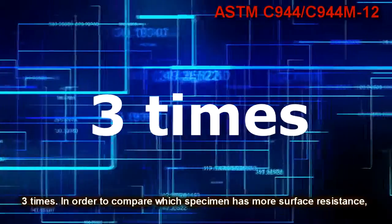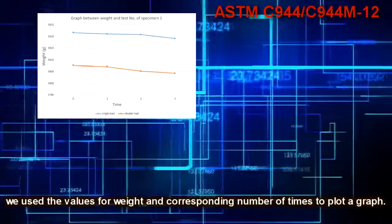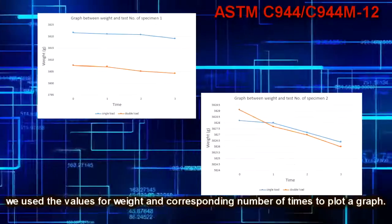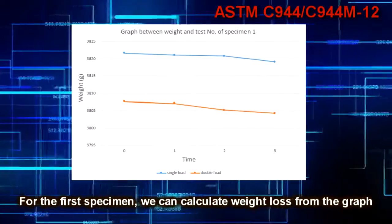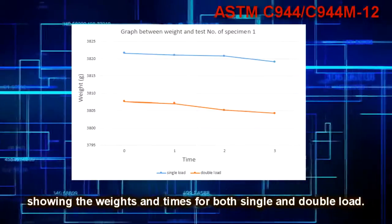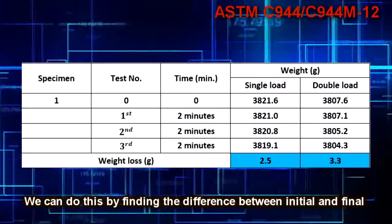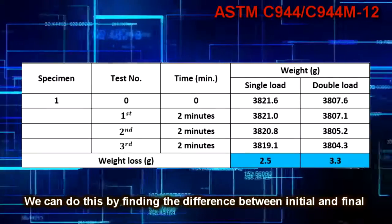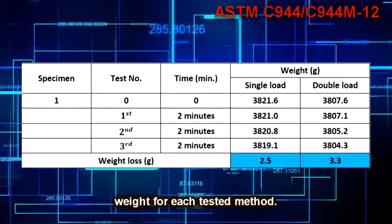In order to compare which specimen has more surface resistance, we used the values for weight and corresponding number of times to plot a graph. For the first specimen, we can calculate weight loss from the graph, showing the weights and times for both single and double load. We can do this by finding the difference between initial and final weight for each tested method.